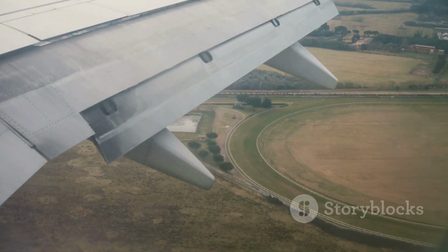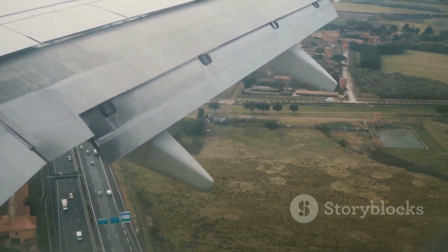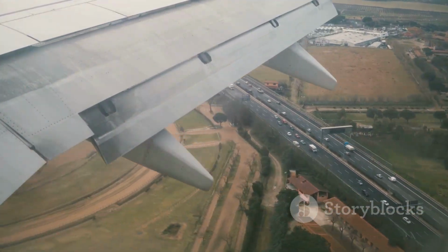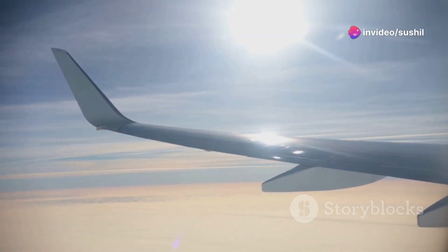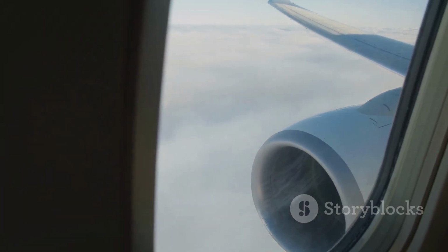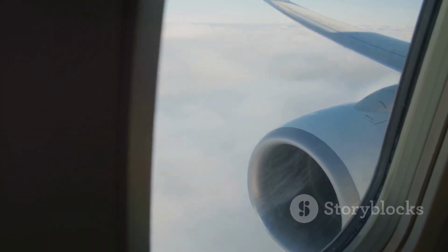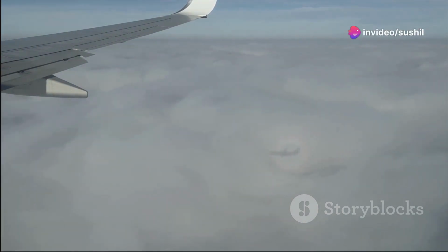Air flowing over the curved upper surface of the wing has to travel a longer distance compared to the air flowing underneath. According to Bernoulli's theorem, this faster-moving air creates a region of lower pressure above the wing. Meanwhile, the slower-moving air below the wing generates a region of relatively higher pressure. This pressure difference, high below and low above, results in a net upward force, lift, that pushes the wing and